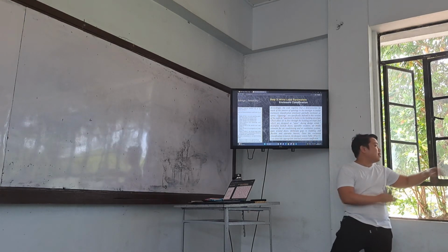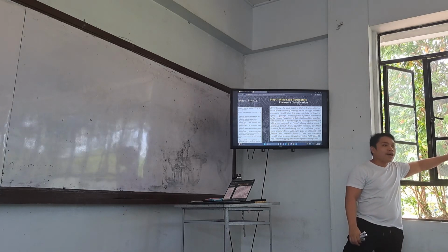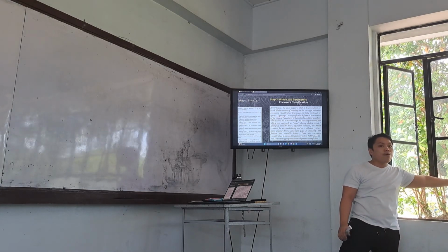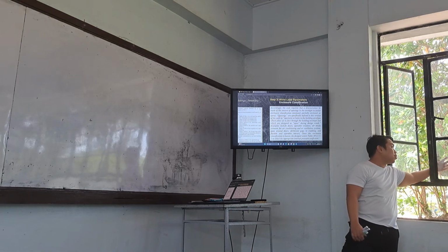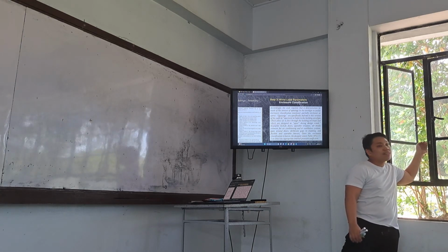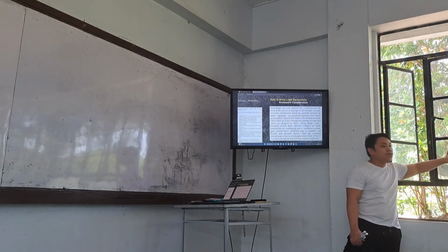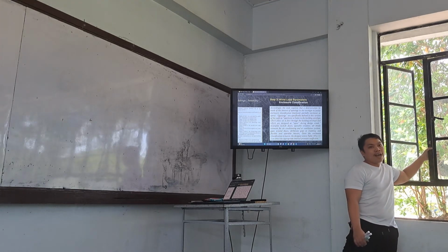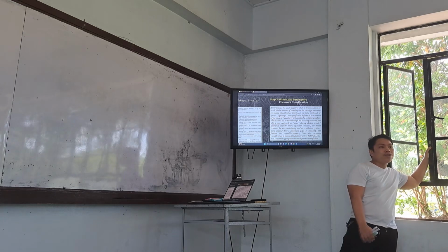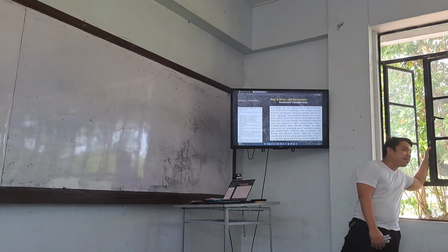Glazings can be broken by debris, thus allowing external wind pressure or external wind to flow inside the building. So regardless of the kind of glass you have, we will consider this as an opening, whether your window is open or closed.